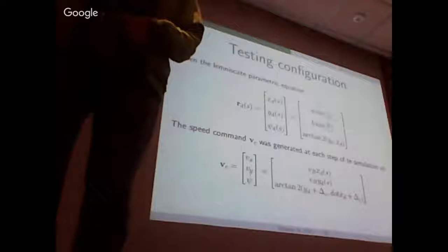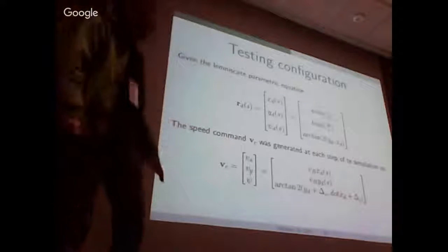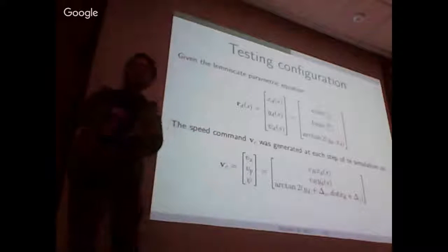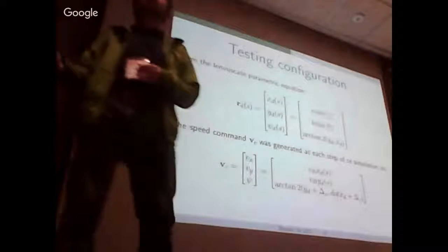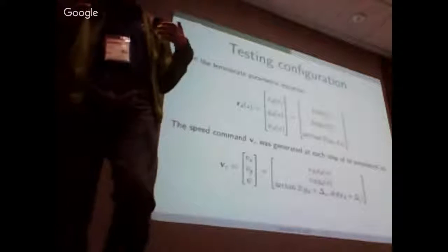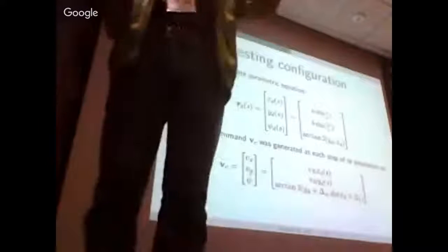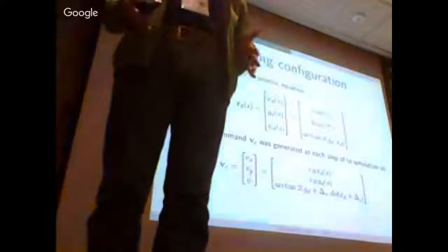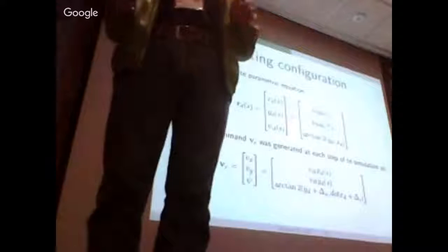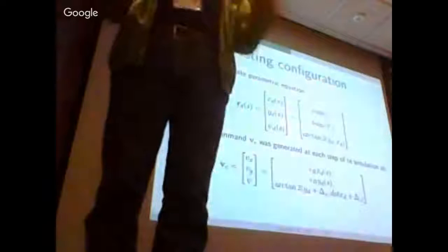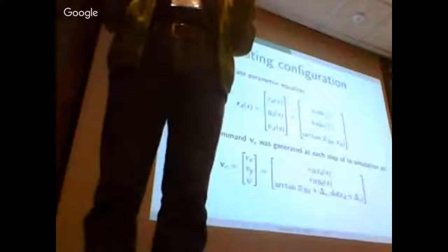I will begin by saying that this velocity command was generated during simulation. Given this velocity command, as I described, the center of mass is propelled forward. From this forward movement, the support tripod is reconfigured to make it move in the desired direction and perform a slip-free motion.